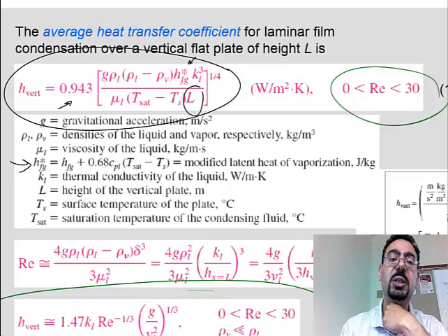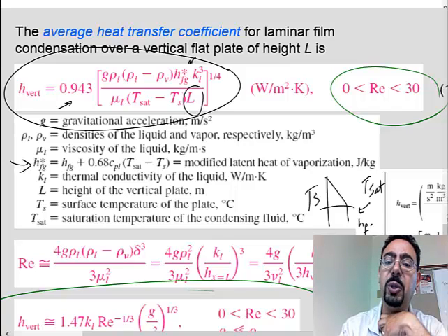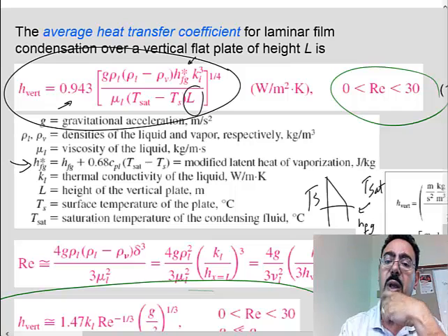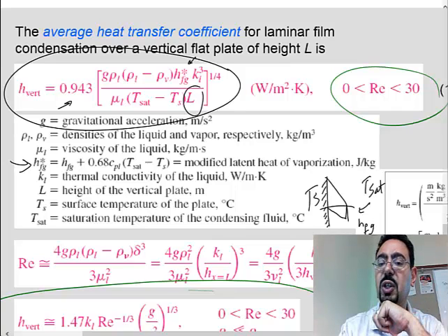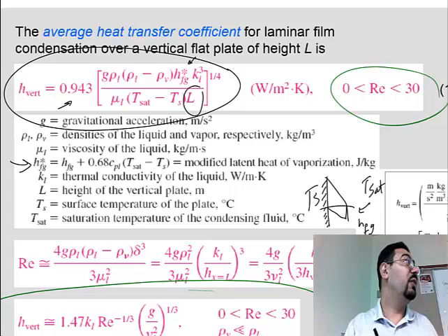Evaporation, that's h_fg, what it's for. But why are they adding more? They are saying that to make that condensation happen, it's not just h_fg that we need to pull from you. We pull even more. Why? Because the film here is not at T saturation, it's at T_s. So not only do you have to take h_fg from them, the film that leaves is subcooled liquid.